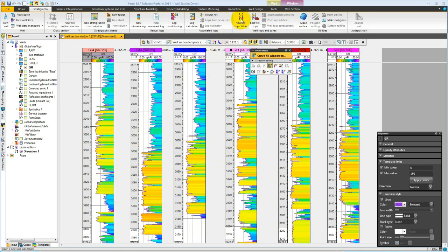Going to the stratigraphy toolbar, we get an icon for new well tops. And if we choose the well top picker, you'll see that in the callout, we can make this a horizon or a fault or another type. There's currently no active surface. So if we start picking, let's pick the sand streak at the top of our sand body.